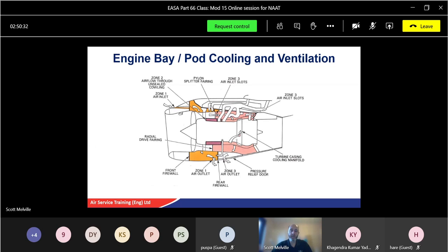So to reduce the chance of a fire spreading in the zone, it's kept at a lower pressure than the other zones. Zone 2 is where the compressor blades may touch the engine casing. So again, a heavy landing, the blades could touch the casing and cause a metallic fire. This is indicated via engine vibration. Health monitoring systems are used. The zone is hotter than zone 1.